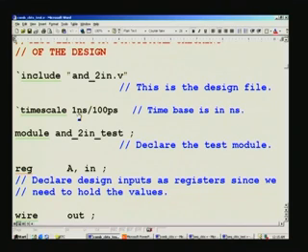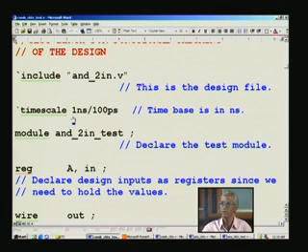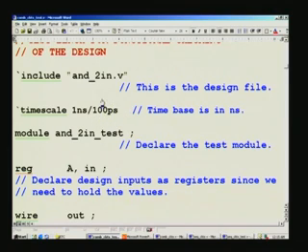So, you use u there, and for picosecond p, similarly m for millisecond, and so on, different timings are there. You can refer to a standard Verilog textbook to get more information on this. How much accuracy or resolution you want is specified here, and this happens to be 0.1 nanosecond, and you can easily get it just by dividing whatever number you have by 1000 in order to step down to the next scale.